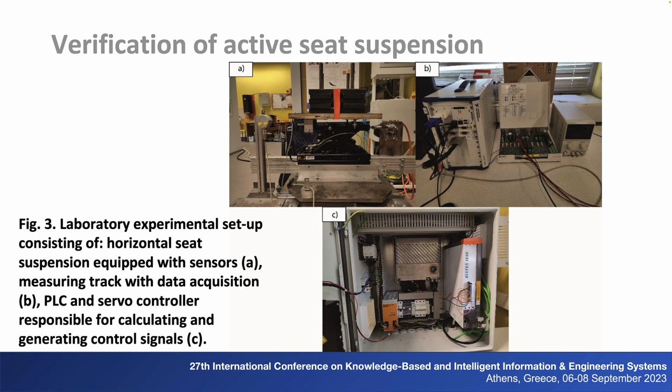The first task is responsible for the operation on data from sensors such as digital filtering, scaling, and calibration. The second one allows to operate the PMSM motor, issue commands and prepares to assign the initial parameters of the motor's operation. The third one is responsible for calculations related to the control system, setting the parameters of the SMC, and generating the control signal for an electric servo drive.